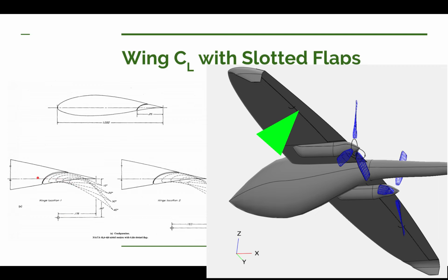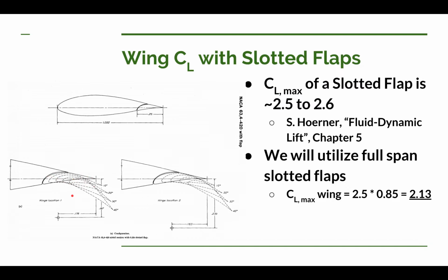Let's say between the engine nacelle and the wingtip, we'll have at least one, maybe two places we'll need to support this flap when it's deployed. Otherwise it's liable to bend and twist more than we want. And in that case, I'm toying with the idea of going ahead and sticking a simple slot up in here with a roller in just the nose. And that would be buried within the wing so it does not have to stick down in the airstream.